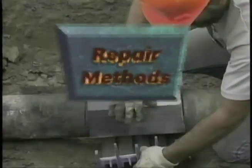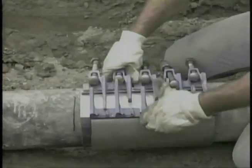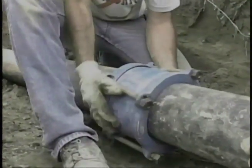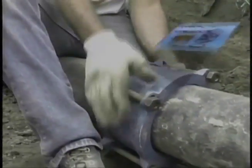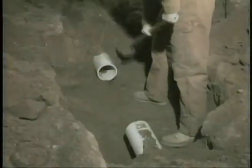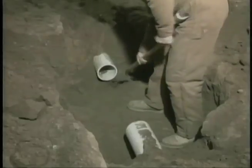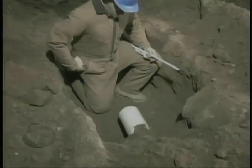Repair methods will vary depending on the type of pipe. There are several types of couplers designed for specific pipes. Most repairs employ couplers that clamp both ends of a replacement pipe section to the original pipe. Dresser couplings may be used on ductile iron, PVC, or pressure lines. To begin repair with a dresser coupling, remove the damaged section. Dig a bell hole that's deep enough to allow clearance and access to the coupler. Measure the overall width of the coupler and clean both ends of the pipe.